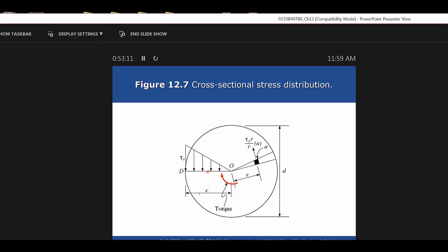I think we did something like that in that last quiz. You had to do this before you could do that on a couple of those problems, so keep that in mind. Also note that the shear stress, if you don't know that, but you know the torque, and you know the radius, and you know the polar moment of inertia, you can rearrange that calculation to get the shear stress, can't you? Well, why would that be important?